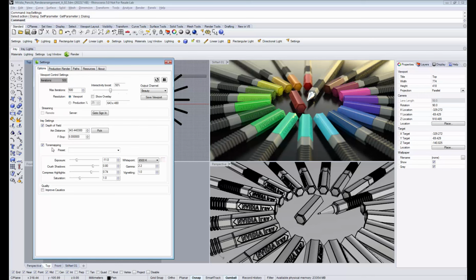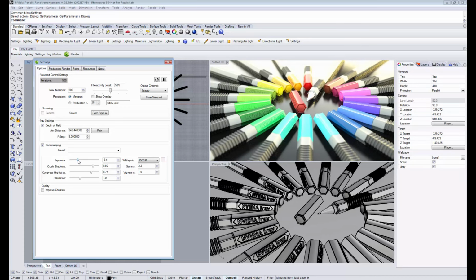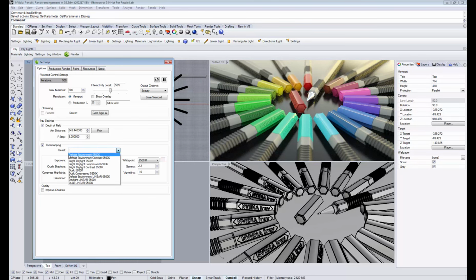And also I want to show that now we have improved the tone mapping workflow. So now you have sliders. So you see you can immediately, very interactively change the tone mapping, and it invites you more to play around and see what effect the changes in the Tonemapper has, so you can achieve the effect of your final rendering quite easily. Also, we have here now a small number of presets.